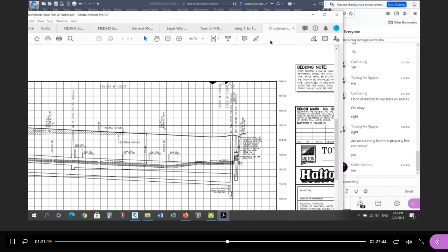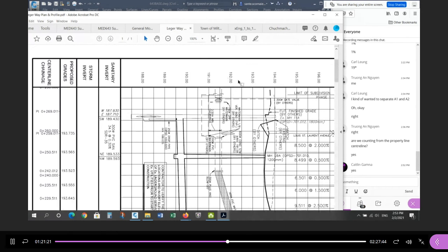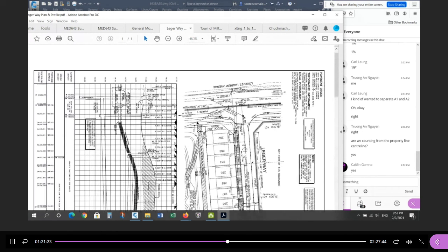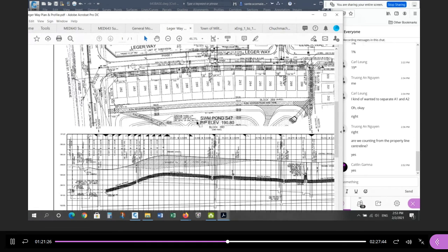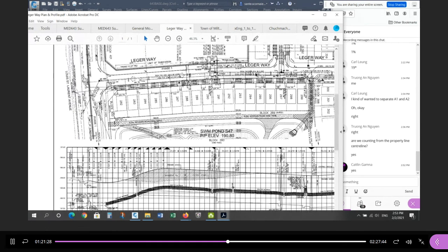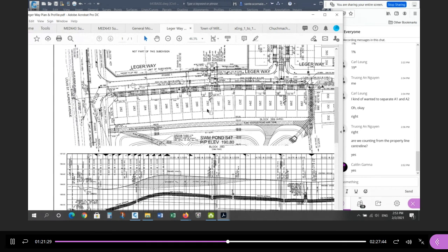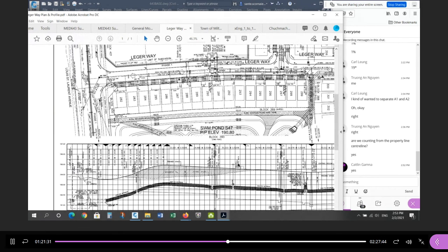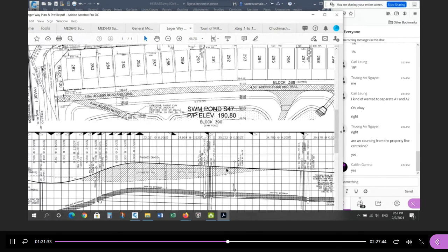Okay. In the past, when I taught this course, I would simply say to the students, from the PDF, do a hand calculation. Figure out what station value on Ledger Way, Street A is, and then interpolate between 2 points on a tangent. Right. So Street A is over here somewhere. We want to interpolate the value. With this model, you don't have to interpolate. I don't even look at the number. I just know that the model is right, and I see the connection point, and I just snap to it. The station and elevation I get for free because I know the model is correct.